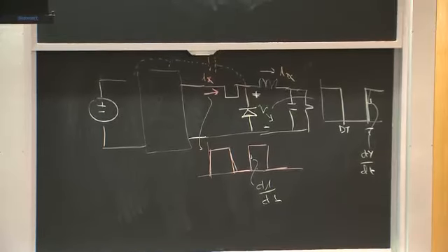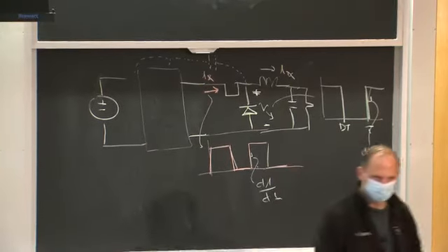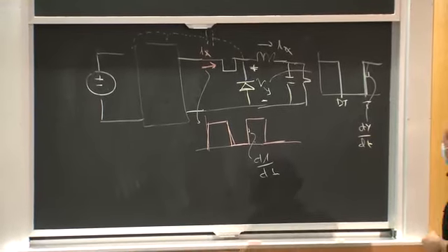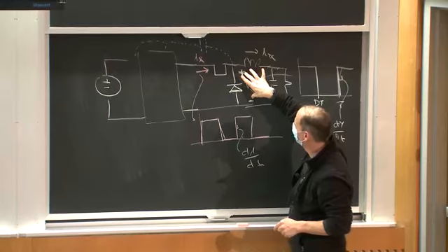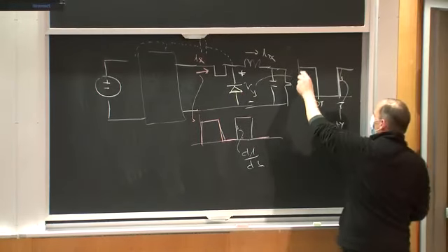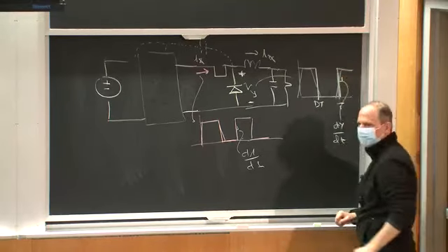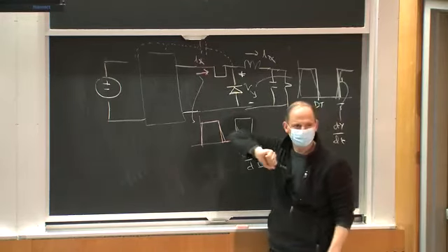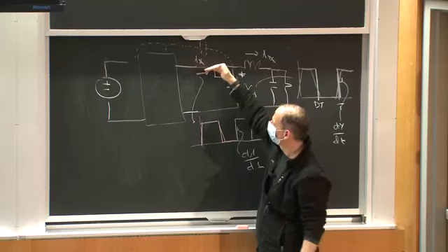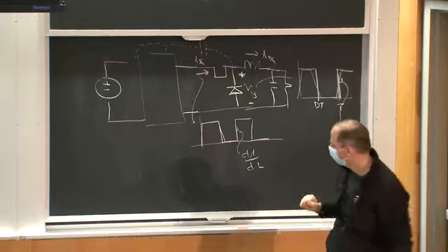So let's think about what's the impact of square wave switching. Because what are we going to do? Maybe if I use zero voltage switching here, instead of having a really steep waveform, Vy, maybe what I would have is a more kind of slew rate limited waveform here, okay? And so what's the impact of this slew rate on dV/dt or the slew rate on dI/dt if I had sort of lower dI/dt switching transitions on the fundamental waveforms, okay?